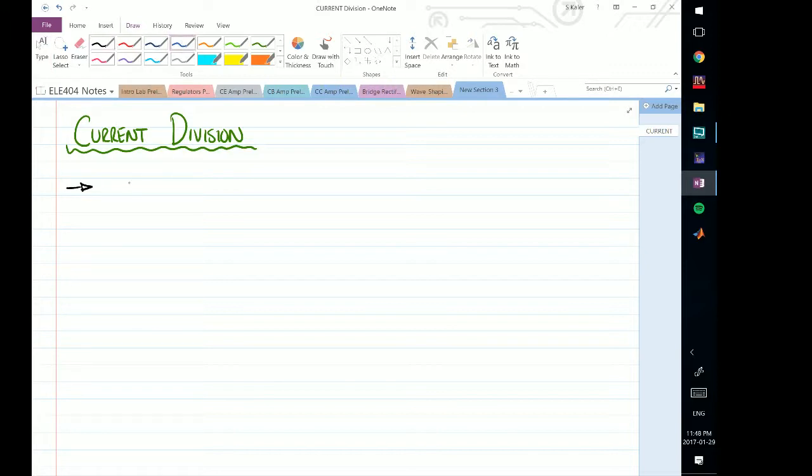So we define the conductance, let's call it G, as 1 over resistance. So any resistor with a resistance of R will have a conductance of G, and the units of this we call, well, for our case will be millisiemens, as we're defining resistance in kiloohms.